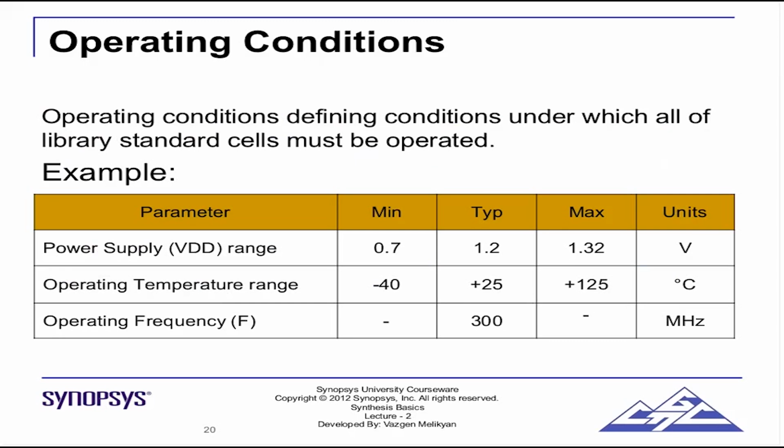So now let's talk about operating conditions. There are three levels of operating condition: process, temperature, and operating voltage. Here the frequency is given. The process is not mentioned here, but let me mention the process also, as we have discussed this earlier. A process can be slow or fast, and usually the process is represented by a 2-alphabet code. The first represents the state of the NMOS, the second tells us about the PMOS.